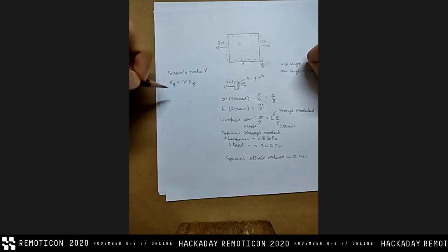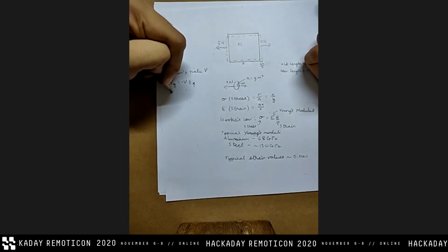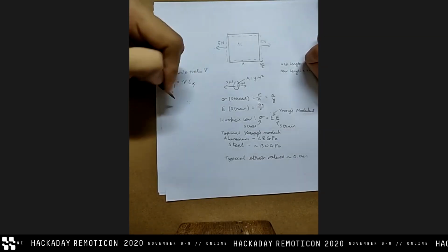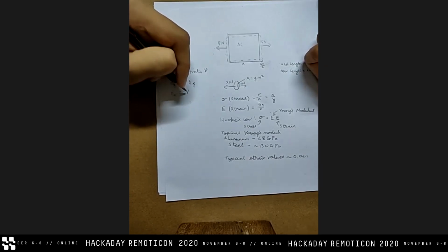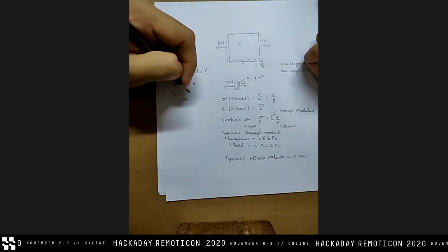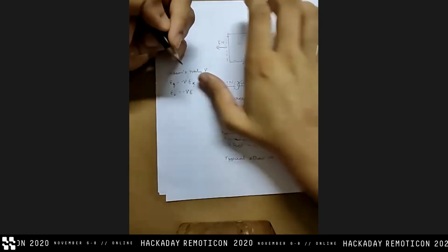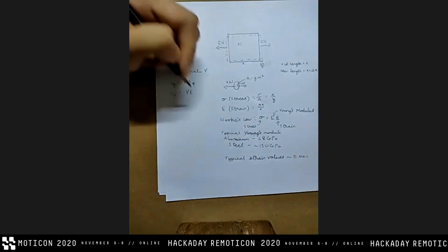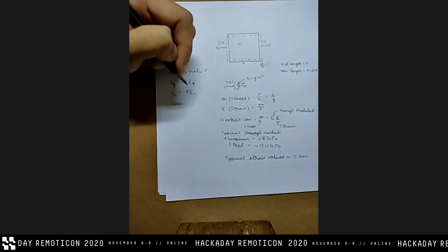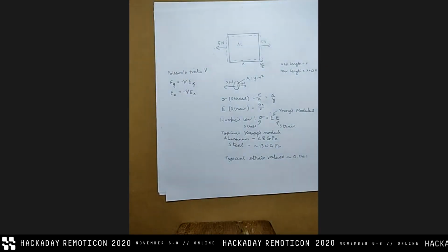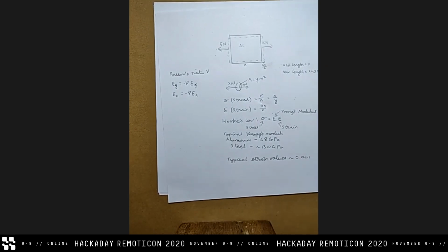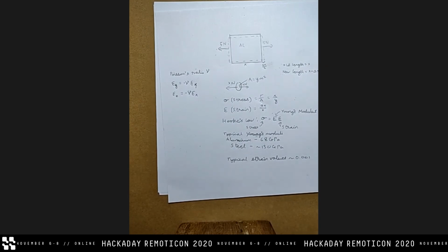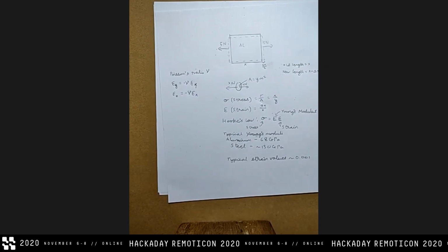And if you wanted to find the strain in z, which is the one you can't see on the paper, that's also equal to this. This is assuming that the material is isotropic. Isotropic is just a fancy word for saying it's the same in all directions. If you're familiar with wood being a grain material, you know that it's stronger if you put forces on it against the grain, and much weaker along the grain.